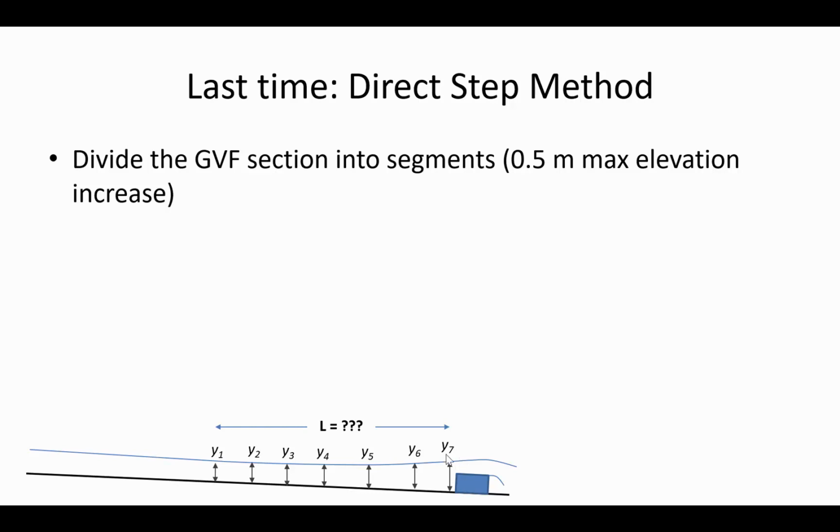And we knew what the depth would be upstream of an obstruction. And so here was a broad-crested weir, and you were given that the depth immediately upstream of that broad-crested weir was 3.8 meters. And what we wanted to know overall was how far upstream do we need to go to where we're going to start to see the normal depth again, where there isn't any sort of pooling occurring.